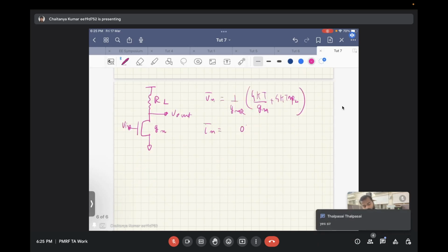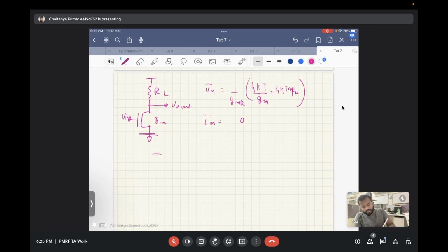Okay, so why cascoding is done: in this problem, we assumed the output resistance of this transconductor to be infinite. However, this won't always be the case. If the output resistance of this transconductor is a finite value, we will see what happens with the whole circuit. So in that case, we use a cascode transistor.